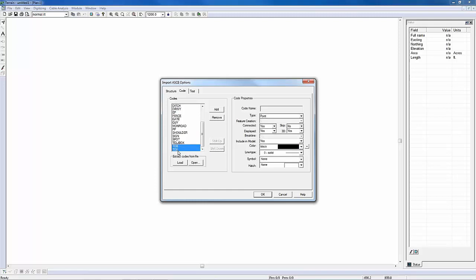I'm going to just select those both at the same time. You can select multiple features at the same time. I'm going to just click and drag across them, connect them all, make them break lines all at once, and choose a green color for both of them. Dash line type, and no symbols at the nodes or at the survey stations.